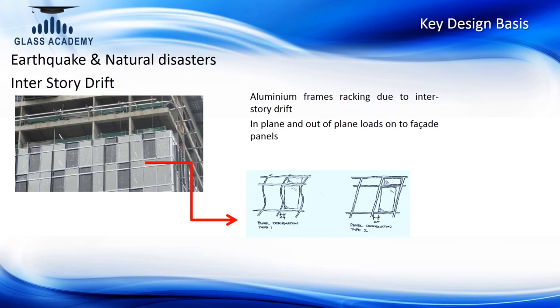But this building sway, how will it impact the glass facade? The frame could also give various modes of acceleration. The frame could have this kind of impact, or it may be linearly leaning towards this. So when the frame moves, it will put a lot of stress on the glass panel or any other cladding material which is holding this. As a structural engineer, they have to check this.